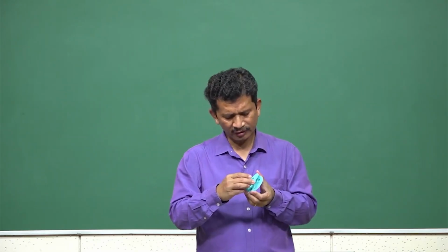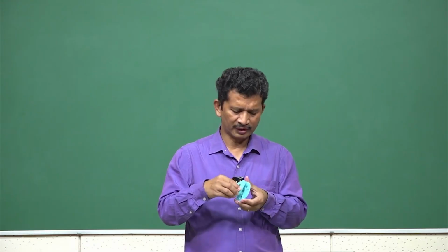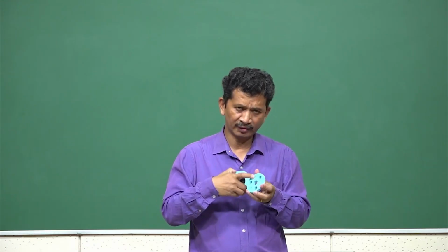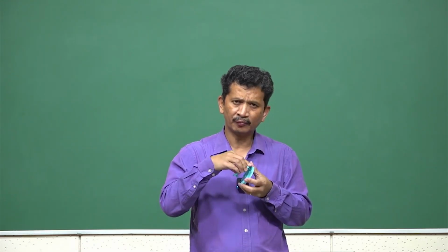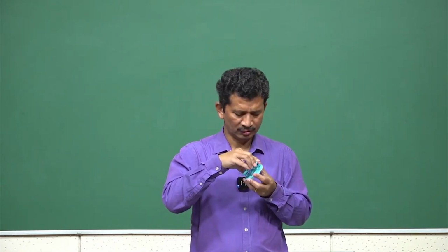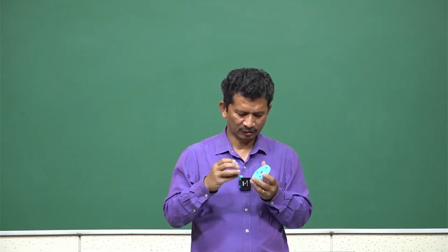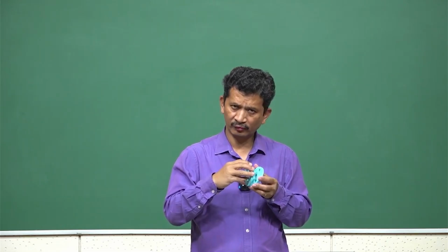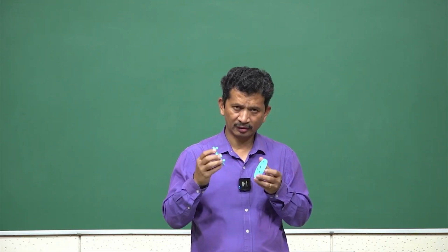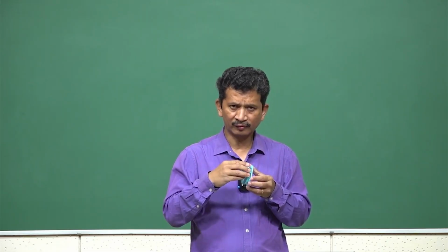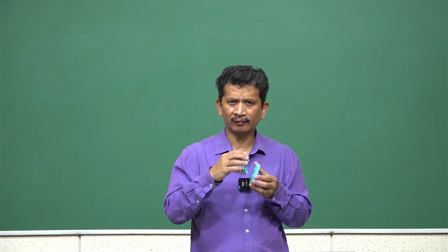What we also observe here is that the location is defined by the trihedral hole, so that point does not move. But if there is any thermal expansion, the other ball can move along the V groove, and the third ball on the flat can also slide on the flat surface.